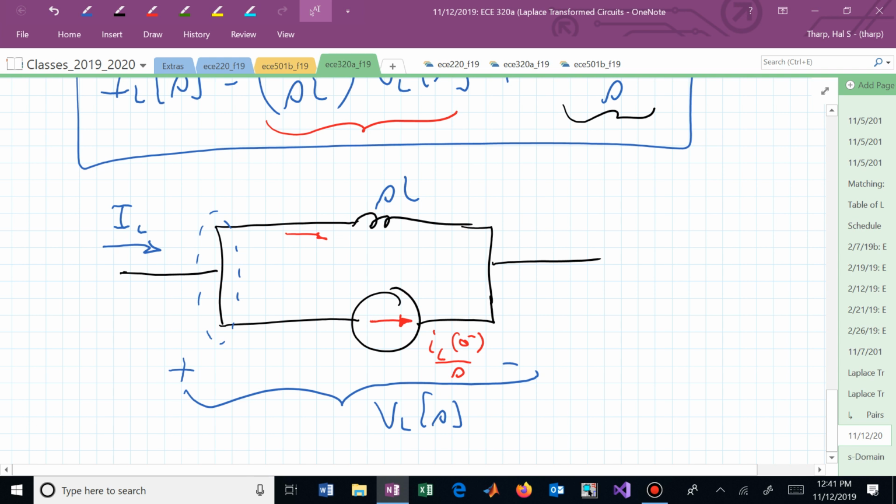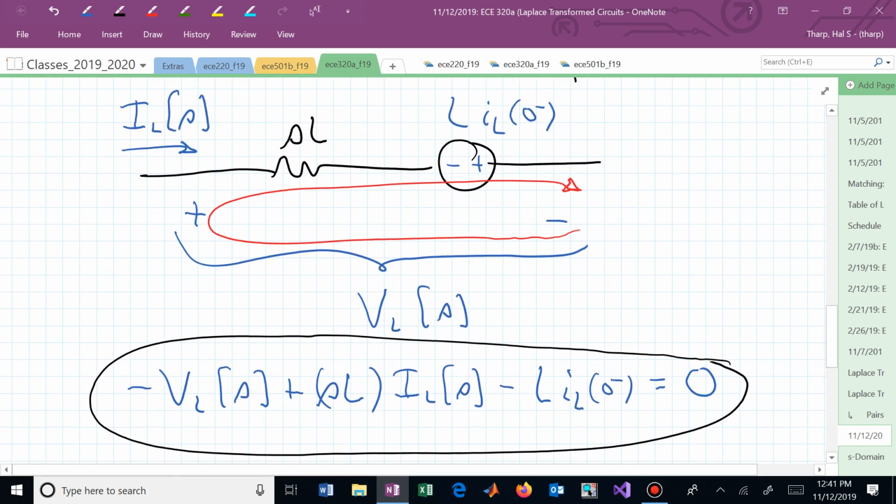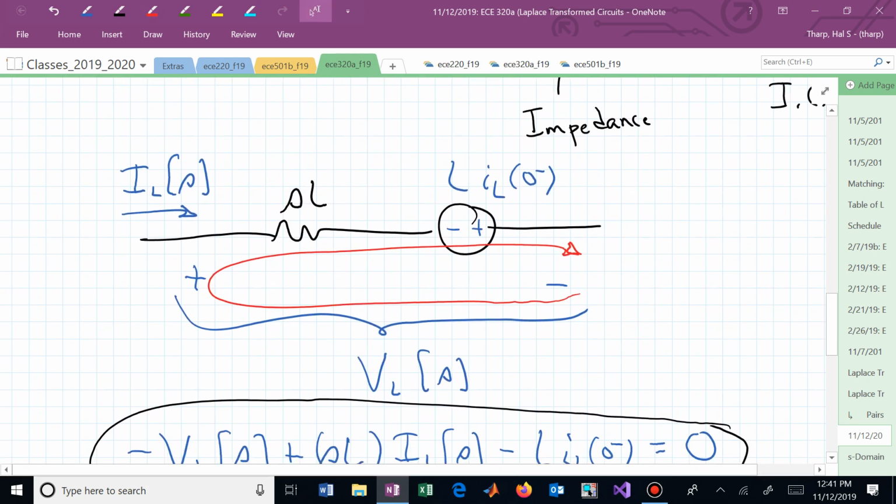Now we're dealing with currents. That's kind of begging node voltage analysis. If we're now doing node voltage analysis, this is the representation you probably want to use to incorporate initial conditions. Do you see, if you have zero initial conditions, that all you have to worry about is the impedance piece, SL? Here, obviously now if I ask, you would know, I need to be doing mesh current analysis if I'm going to put a series voltage source to accommodate my initial conditions. Yes?